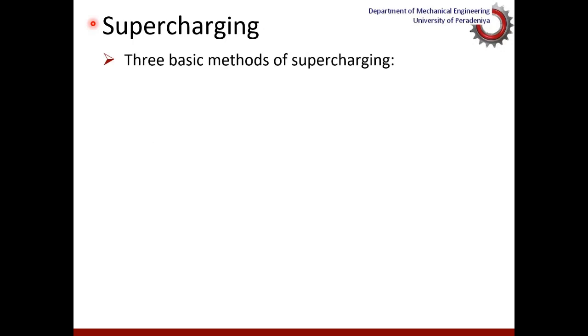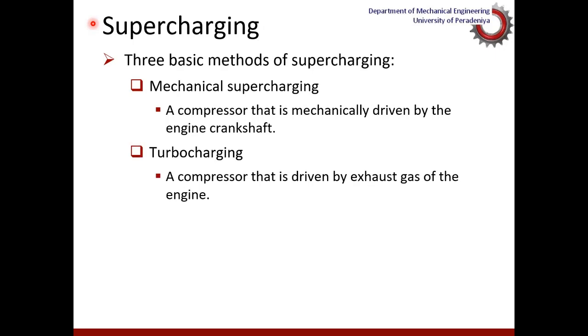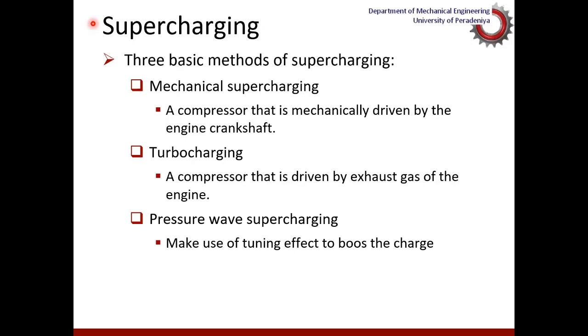So there are three basic methods of supercharging. One is the mechanical supercharger, where you connect a compressor directly to the crankshaft, attached to the intake system, so that you can suck air into the cylinder. And then turbocharging, it's more or less the same thing, but the compressor is not connected directly to the engine crankshaft; the compressor is driven by the exhaust gases. And then the third type is the pressure wave supercharger. Mostly, this type of supercharger makes use of the tuning effect to boost the charge.